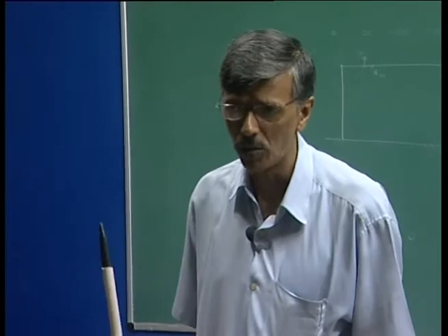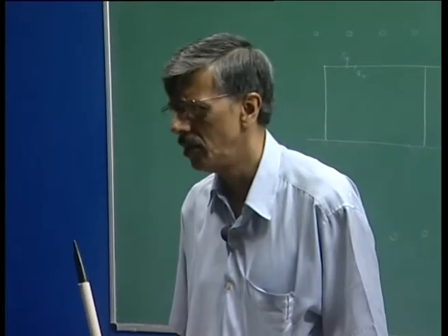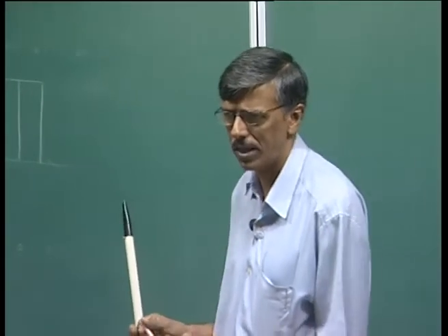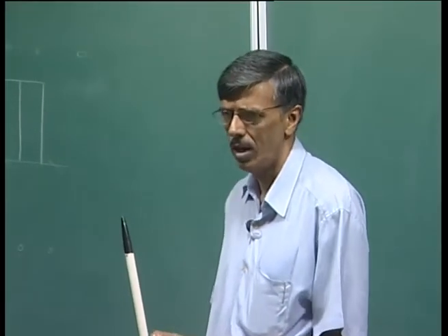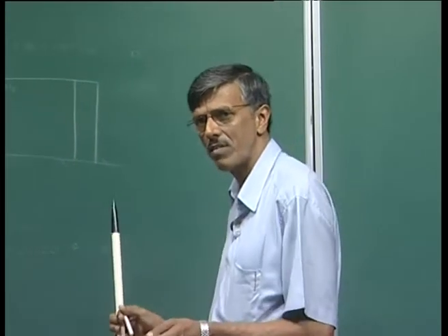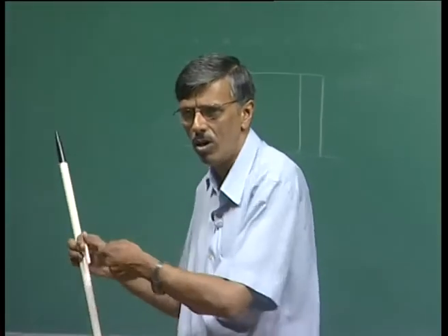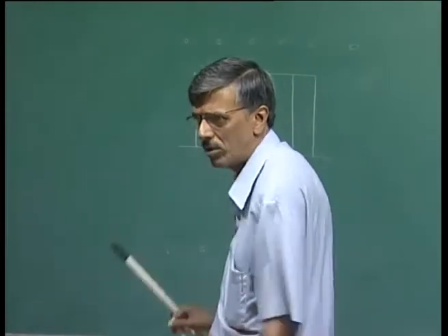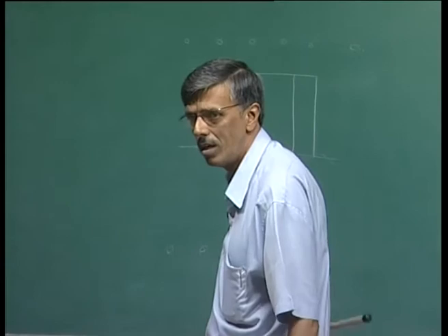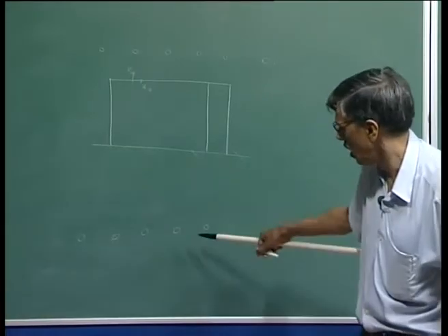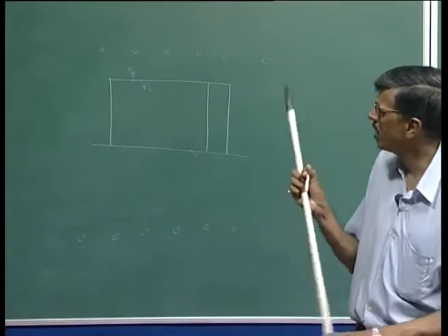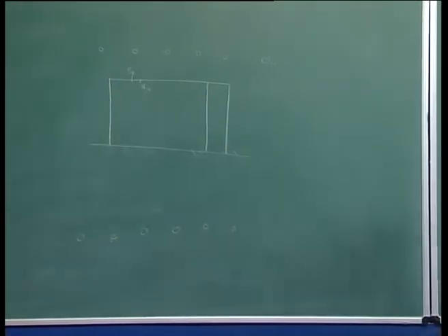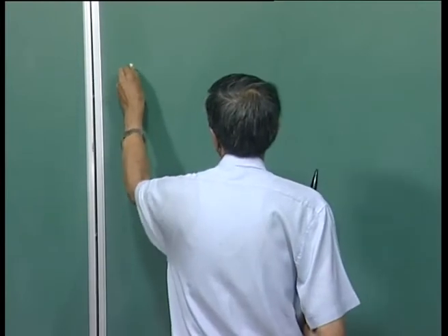Now, if you have followed the effect of irrotational vortices, you know you can use the Biot-Savart law and calculate the effect of an individual vortex. Then the individual vortex effect could be integrated over the whole sequence. So we have an infinite array of vortices along with the image system, and that I could do. You can look at the book by J. M. Robertson.